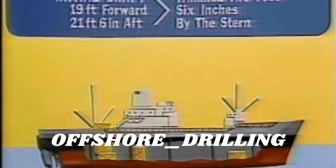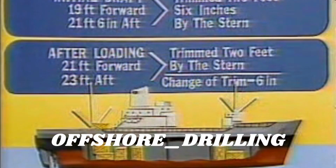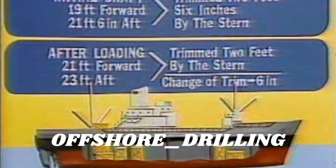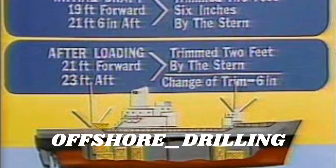In problem 3, we have drafts of 19 feet forward and 21 feet 6 inches aft. So the vessel is trimmed 2 feet 6 inches by the stern. After loading, we observe the draft to be 21 feet forward and 23 feet aft. The ship is now trimmed 2 feet by the stern. Both trims are by the stern, so we subtract them to obtain a change of trim of 6 inches.